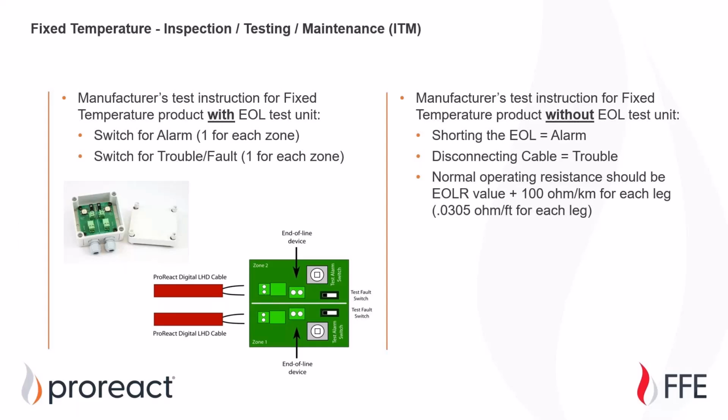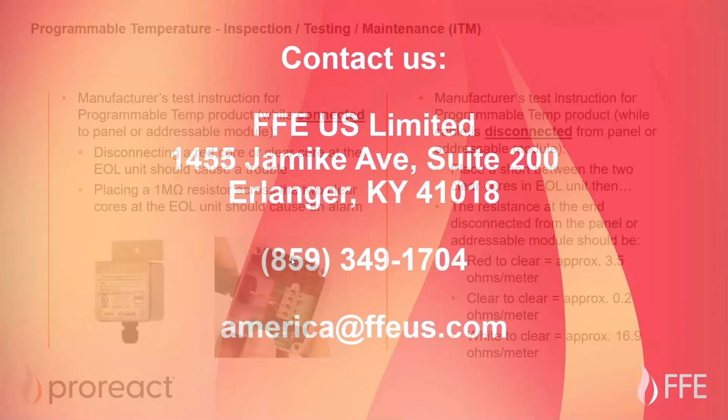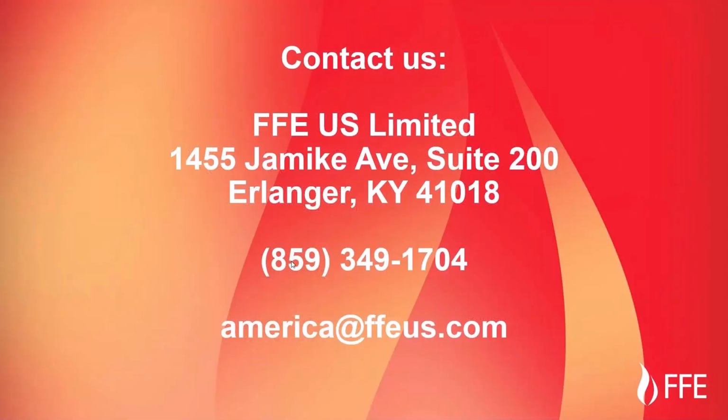signs. And it also appears here too that you can do the old, I'll refer to it as the NEC trick. You can meter the resistance across those legs, and that'll give you the approximate distance from where you're at. So. Yeah, exactly. Good point.